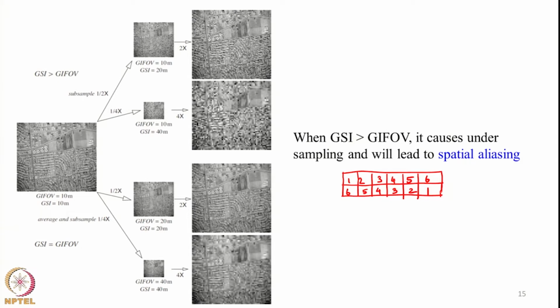Okay, 2 scan lines. So this is scan line 1, this is scan line 2. Now I am going to have a system, let it be like a whisk broom, where the sampling interval in both across track and along track direction has to occur, because the satellite in across track is moving like this, and the satellite is also moving like this, in the along track direction. So, a continuous stream of energy will always be coming in, hence the sampling has to occur in 2 dimensions.